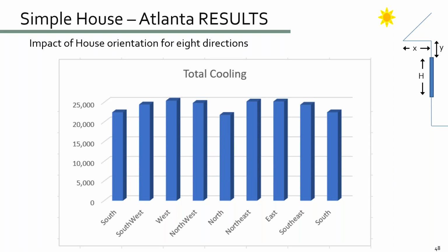I don't know how they price out, but there are other load calcs that you can do. They're not necessarily ACCA approved. That doesn't mean they're wrong or incorrect, but if you're doing it for a program, it probably needs to be ACCA approved. So I would just say go to ACCA's website and see what they say. Good question. I've used most of them, and I don't have any great preference for one over the other. I think for a block load, this was fine. For a room by room, this one's a little bit clunky. You can do it, but it's more clunky. But if you use it enough, you get pretty good at it.